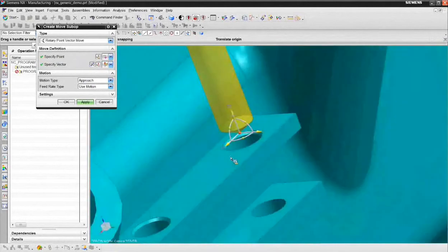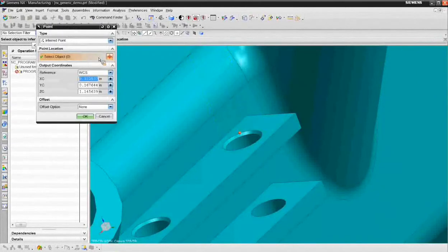If you wanted to go to an exact and an associative value, you'd use the point constructor. You'd go to the point dialog, and you'd open up rectangular offset, select the point, and then that point would be associative. Or you could create the associative points ahead of time, which would be another option. We're just going to use locations on the model.